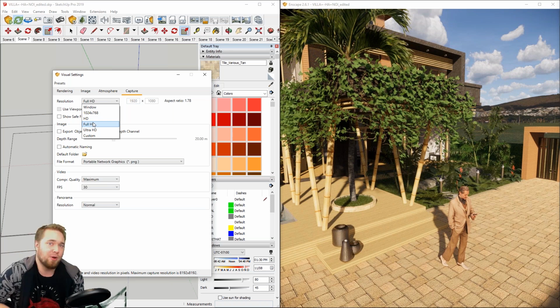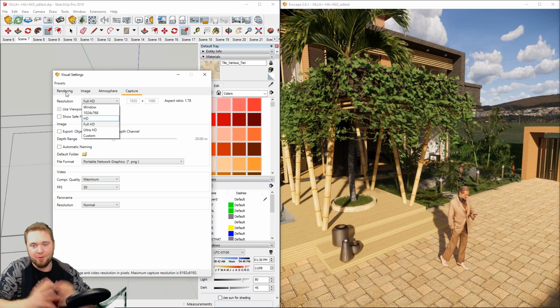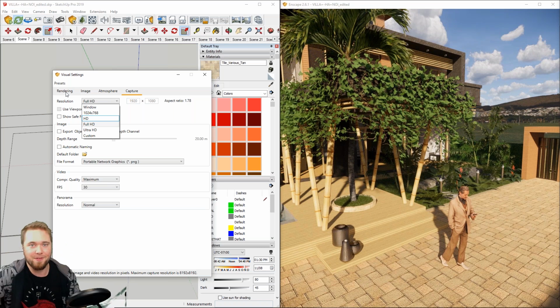It might also be the case that you have a very long video. Since Enscape is rendering videos incredibly fast, like 30 seconds easily in 3, 4, 5 minutes, we've seen some people suddenly trying to render 30 minute videos or something like that. And your graphics card has to store every single frame of that in its own RAM during the creation of the video. So if you make very long videos, at some point your graphics card is going to crash because the RAM is full. So I assume the problem will be somewhere there, Fabrizia.